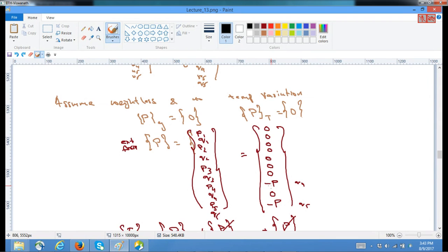And if you want to consider the self weight and the temperature variation, I would suggest that we have discussed earlier how to handle the gravity forces and the temperature forces. For gravity forces, the weight consideration is equally distributed to each node connected to it, and the temperature variation follows minus C, minus S, C and S into E alpha delta T, which we have discussed earlier.